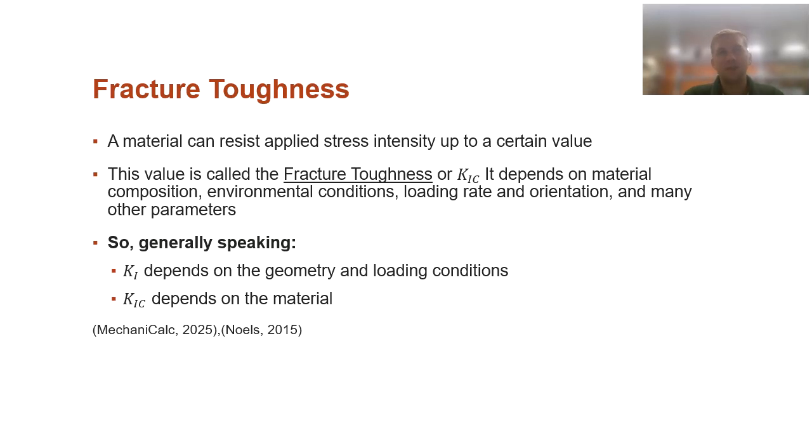So we have this mode 1 fracture, mode 1 stress intensity, K1, and when that reaches a certain point, it will break. That point we call fracture toughness, K1C, C being the point that it'll fail, the ultimate point, and the K1 being the stress intensity in mode 1.